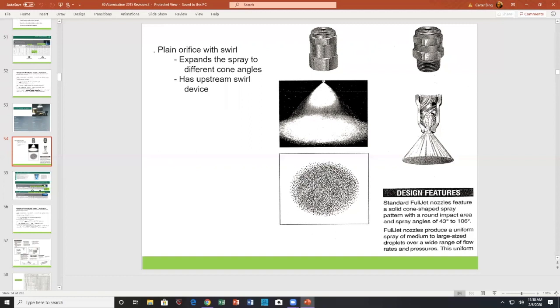Now, you should also recognize if you're spraying slurries, that this static mixer may disappear over time, and your nozzle may be worn open, basically, and be just abraded away. Abrasion starts around 30 feet a second. At 60 feet a second, you have full-on erosion going on. So it gives you an idea of what velocities you should pay attention to.